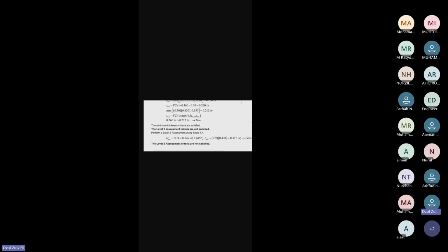Okay. So let us recap lah part 4. Part 4 recap is, let me go back to this graph. Okay. Part 4 recap. Basically measure thickness in grid. Calculate the ratio. Ratio adalah tempat paling teruk versus tempat yang okay. And then calculate the length that is okay for us to do this averaging. Sum up the area, average kan, jadi an average thickness. And then compare balik average thickness against the original T-min. If tak lepas, tak lepas lah. Okay. So that is it for part 4.